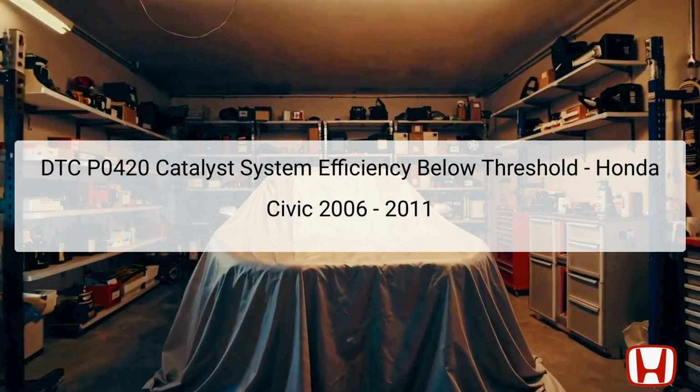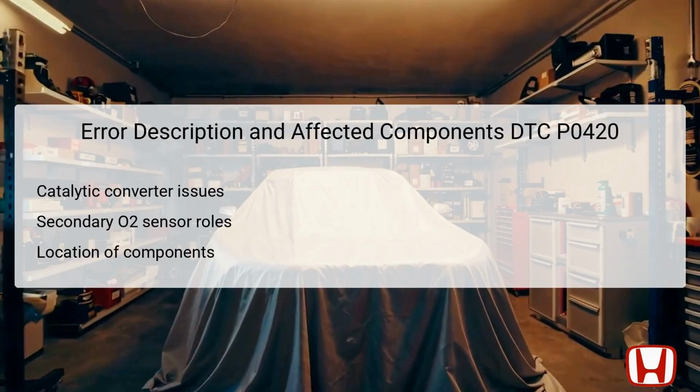The error associated with DTC P0420 is primarily due to the performance issues with the catalytic converter. This component is integral in meeting emission standards by transforming harmful exhaust gases. The secondary oxygen sensor, HO2S, located downstream of the catalytic converter, monitors its efficiency by comparing the oxygen levels in the exhaust before and after the catalytic conversion process. If the sensor detects that the converter is not operating within the required thresholds, it triggers the DTC.